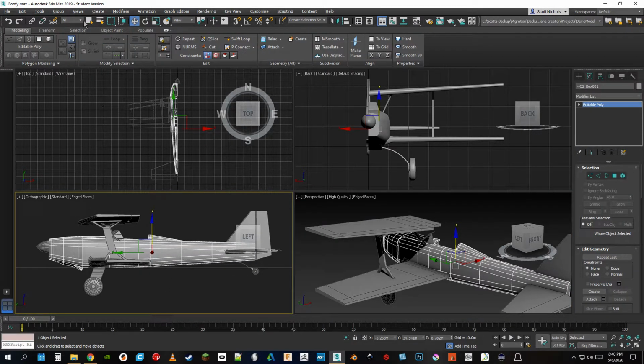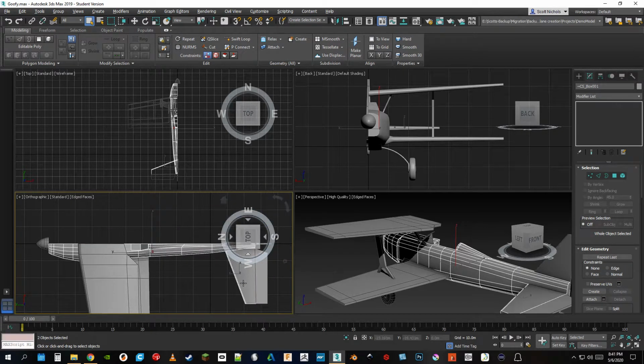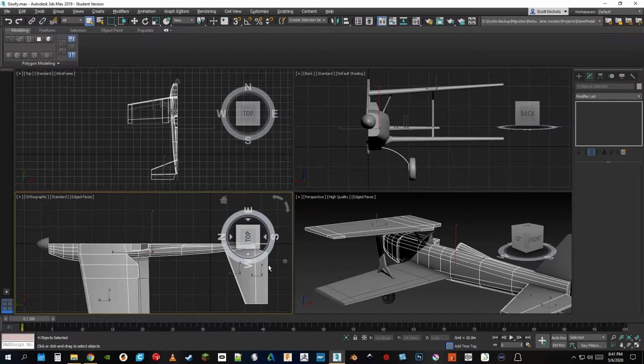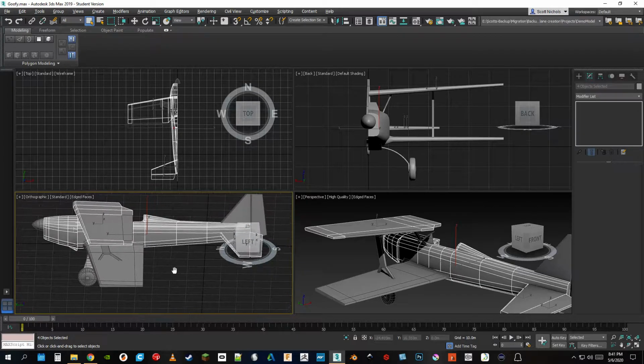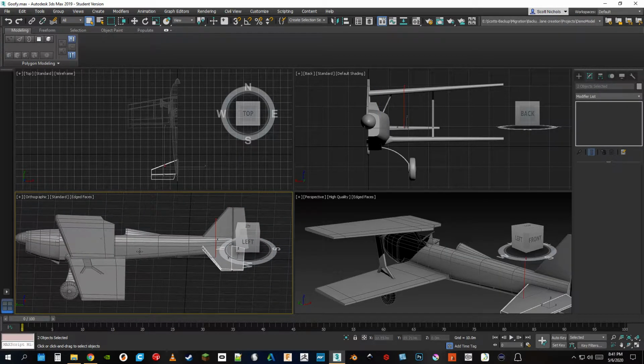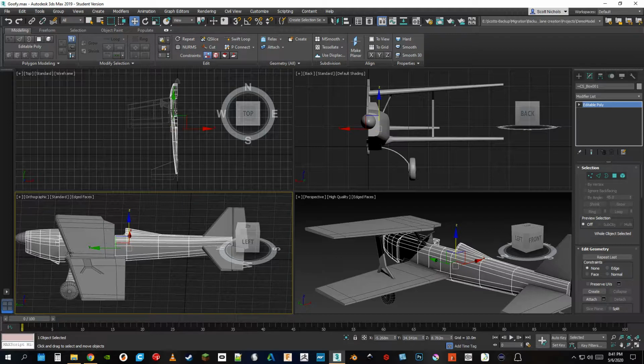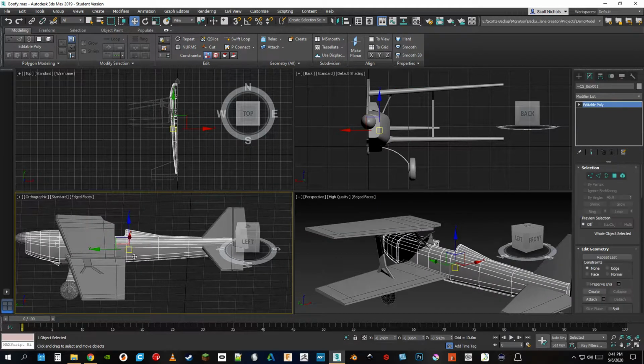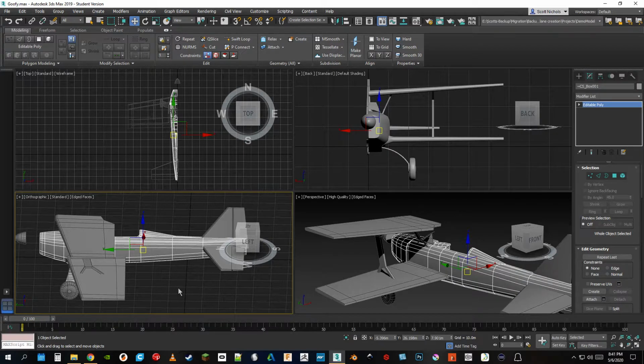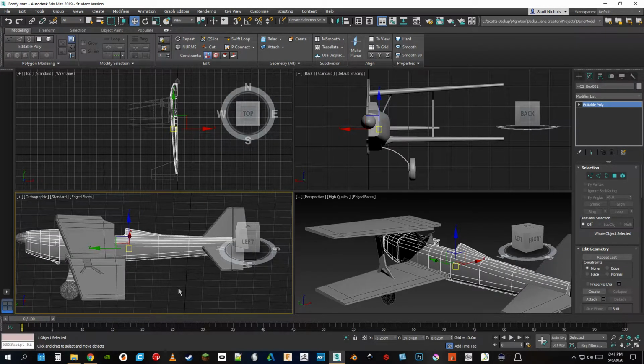So if I'm on just the regular selection, which is the way you're going to want to do that, you can hold Control and you can select different objects here. As long as you're holding Control, you continue on your selection. If you hold Alt, you'll unselect particular ones. And it's a lot better than having one of these manipulator tools active, because if you had the move tool active and you were selecting around, you can easily get things moved out of place, and that can become a problem.